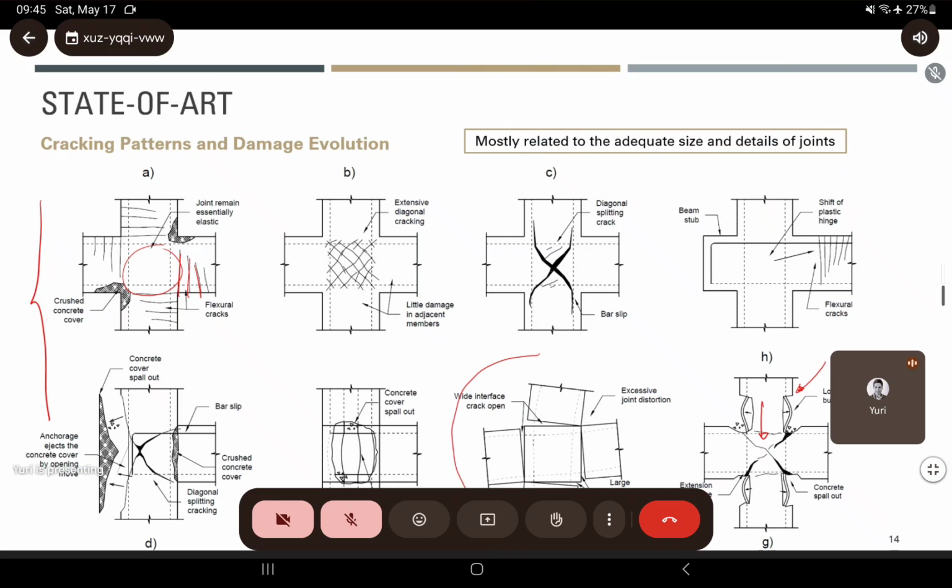We also categorized and assessed the failure of the joint because we think that is also an ultimate limit state, not necessarily just a service limit state, because it will impact the overall response of the building and can create an eventual collapse.